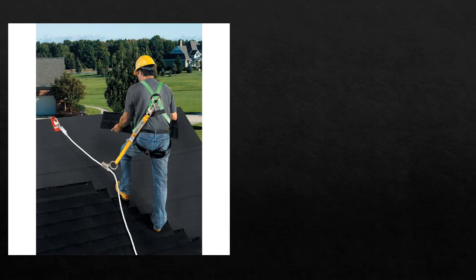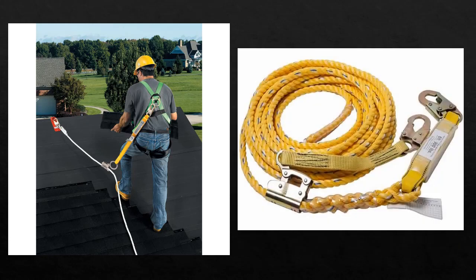This is an example of a system where the person working at heights has their travel restricted by the anchorage system they have. In this case, the anchorage system is a long cable that has a device that attaches to it, and if it senses a fall or any kind of pressure, it locks up so that a person is not exposed to more than just a very short fall. So it limits your freedom of movement a little bit, but it's a very effective system, especially if you're going to work on a highly pitched roof like you see in this example.